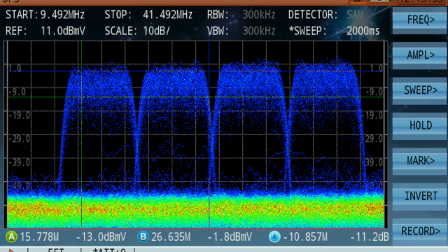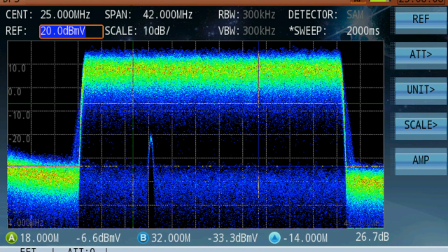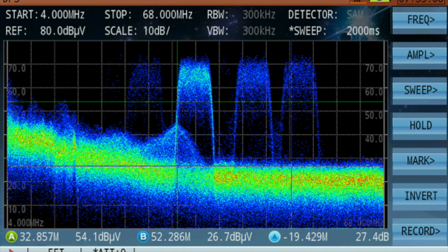The objective is to hunt return path test points, typically optical, that are having difficulties, and that is very easily confirmed with a visual inspection. This picture shows a typical OFDMA signal transmission with a very low and short linear distortion. Once a node with difficulty is identified, start by saving this trace for later field comparison use. The technician can then move to the specified node in the field to isolate the impairment location.